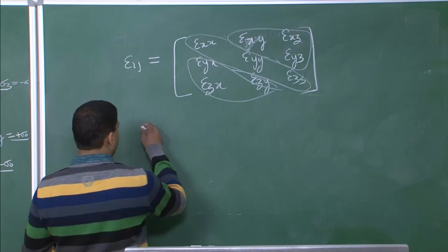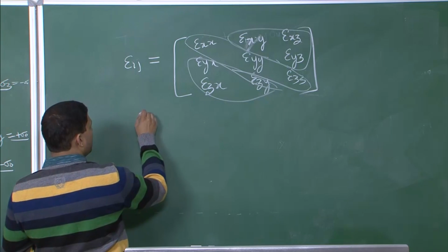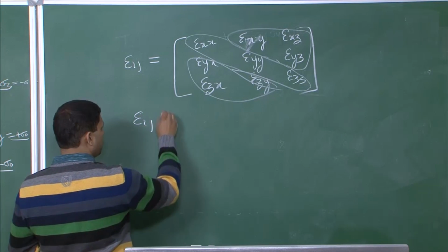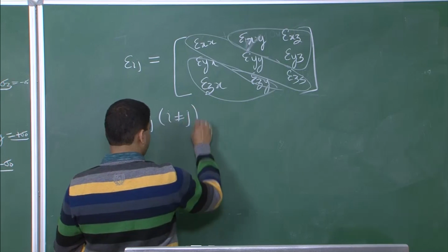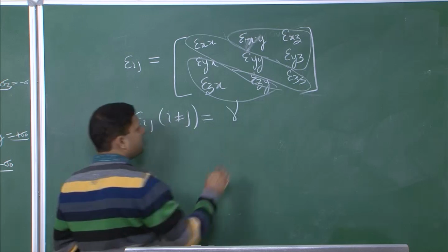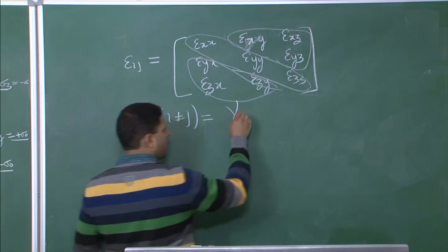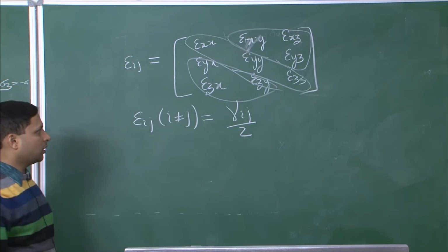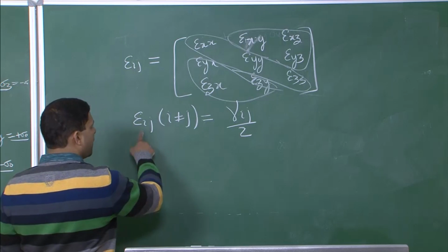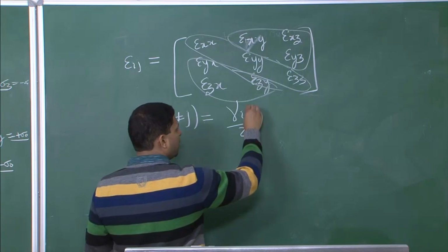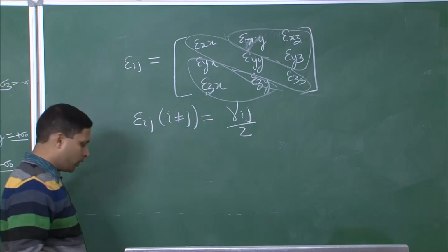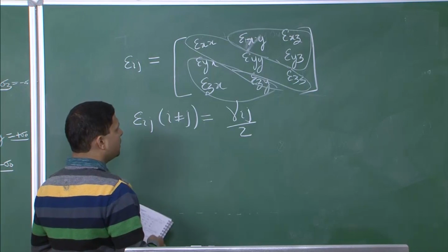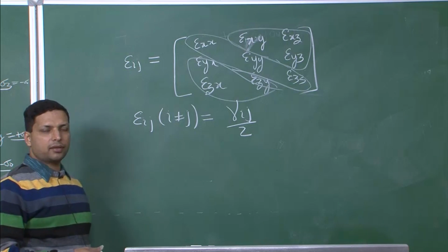Another thing you need to be aware of when we are talking about strains is that for the shear strains, when i is not equal to j, what you measure is usually gamma, okay, and that gamma ij by 2 is what is taken in this tensor matrix, tensor table. So, epsilon ij, where i is not equal to j, is actually gamma ij by 2. That is one thing that you need to be aware of. And another thing is that you must be aware that strains are path dependent.